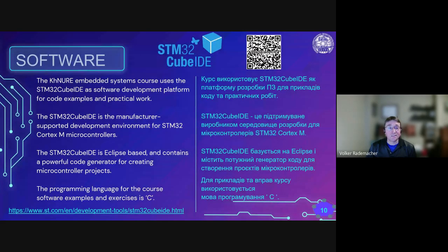Very often, the application of an embedded system prohibits the use of these object-oriented features because most of the time they use dynamically allocated memory on stack and heap. And in many applications, this is simply not practical because the question is, what happens if the system runs out of memory? A PC can simply throw up a message saying, I'm out of memory, buy me more memory. An embedded system cannot do that. It has to continue to work.